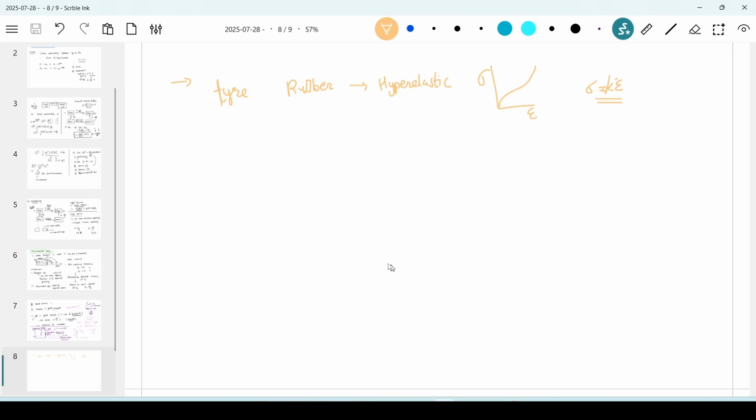Then you have buckling problems. Like you have a constraint here and you are applying some force here, and there is buckling happening. So this is also non-linear, because there are large displacements and rotations, not large strain. We will see these different types of non-linearity as and when we discuss this complete module 3, 4, 5. These are all non-linearity, so we'll discuss one by one.